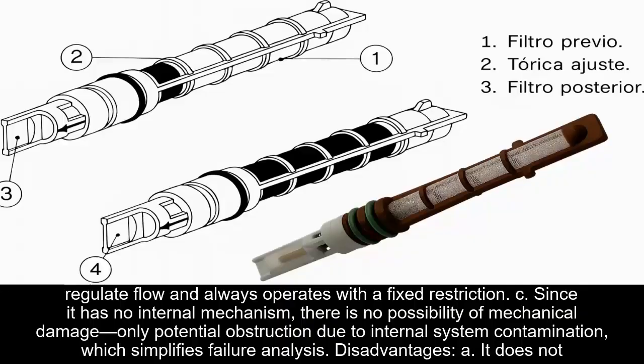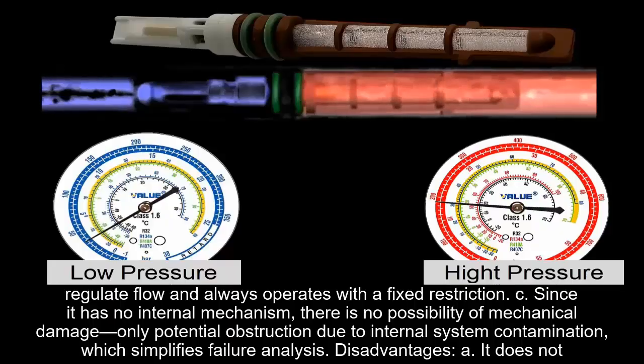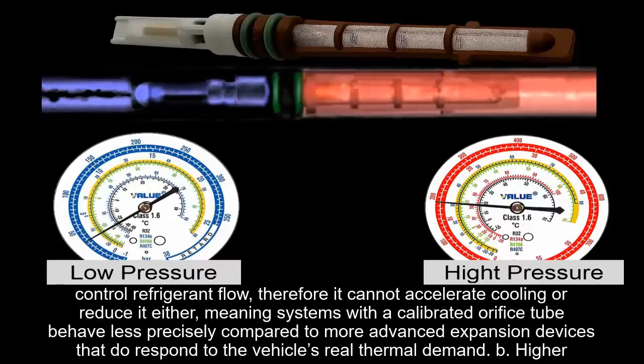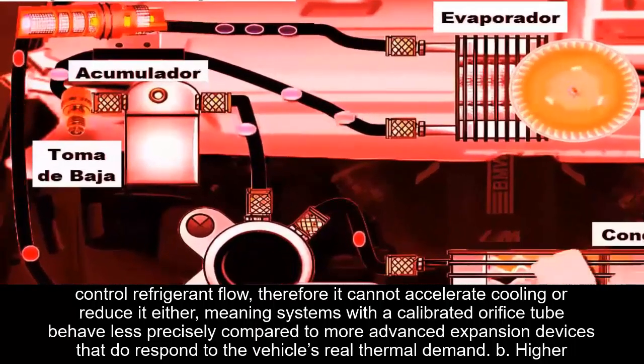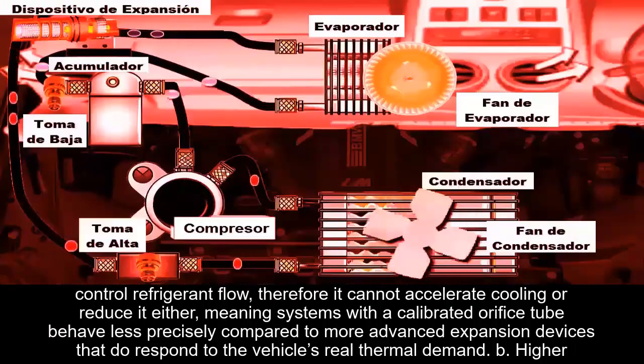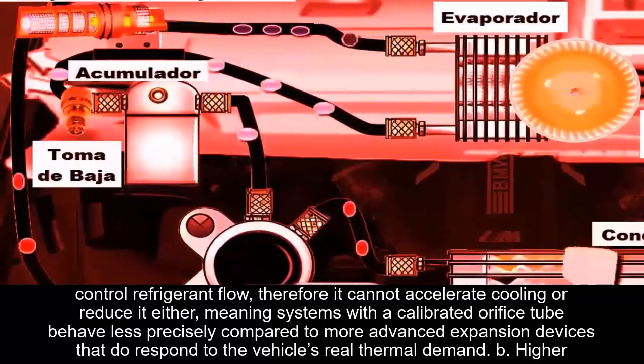C. Since it has no internal mechanism, there is no possibility of mechanical damage, only potential obstruction due to internal system contamination, which simplifies failure analysis. Disadvantages: A. It does not control refrigerant flow. Therefore, it cannot accelerate cooling or reduce it either, meaning systems with a calibrated orifice tube behave less precisely compared to more advanced expansion devices that do respond to the vehicle's real thermal demand.